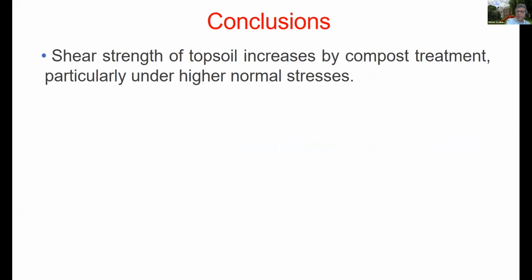In conclusion from the first study that we finished, we figured out that the shear strength of the topsoil increases with compost treatment. That was more obvious if we increase the normal stresses. For us, the superficial application would require low stresses, obviously.